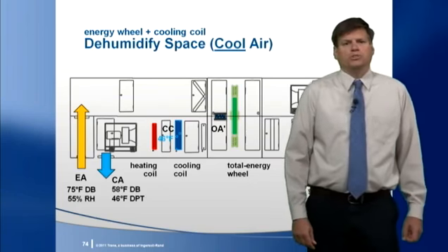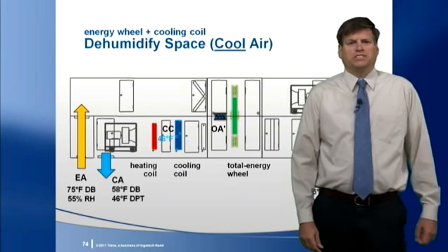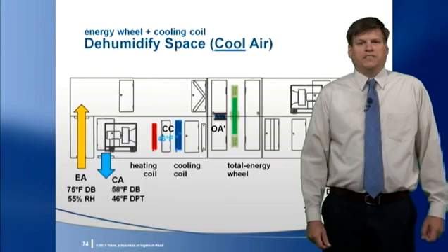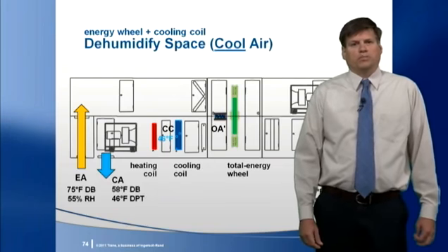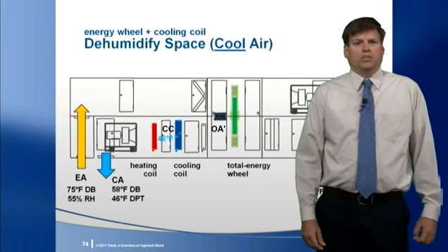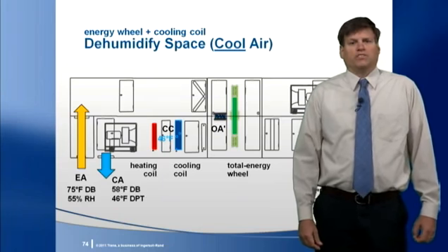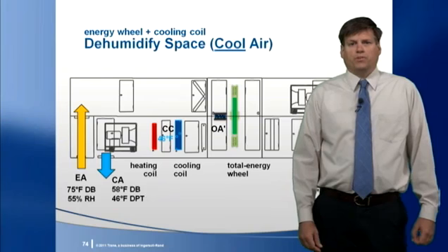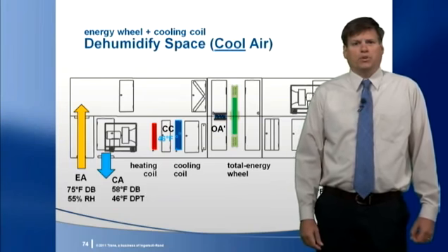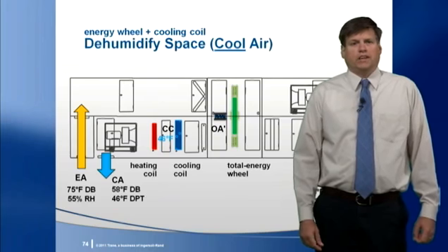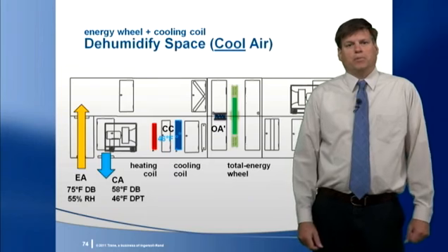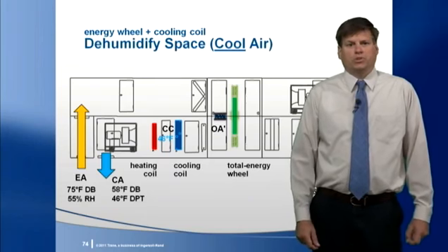For those who want room neutral air, the air would be reheated to something like 70 or 75 degrees. In either case, even if this heat is recovered from the condenser or from some other source, this reheat will not be free, as it also comes with a cooling cost. For every 12,000 BTU per hour of reheat added in the dedicated outdoor air unit, it will add a ton of cooling to the overall system. This may also add to the fan or pumping energy for the system, because the space sensible cooling equipment may now need to provide more cooling.